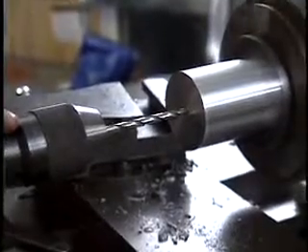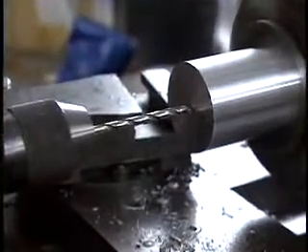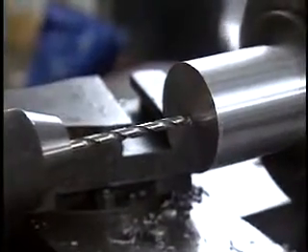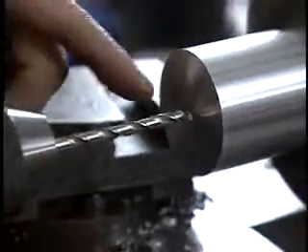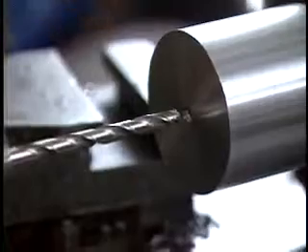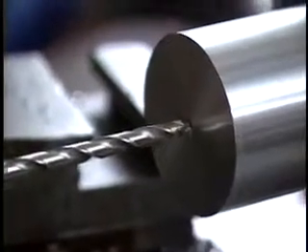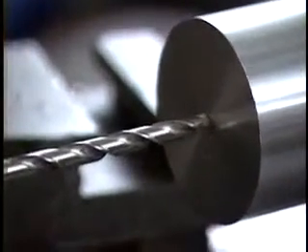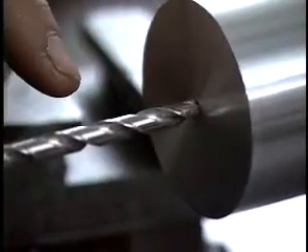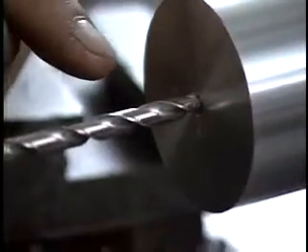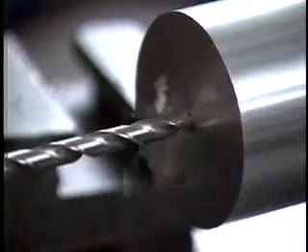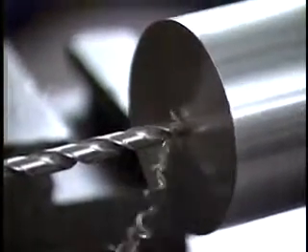It's important to start slowly here. The drill is slightly off-center, and it may be because the tailstock may be slightly out of adjustment. One flute may catch a little bit before the other and pull the drill to the side. So if you start slowly, the funnel will draw the drill accurately into the center of the hole. You could see the drill jump just a little bit as I brought it in contact.